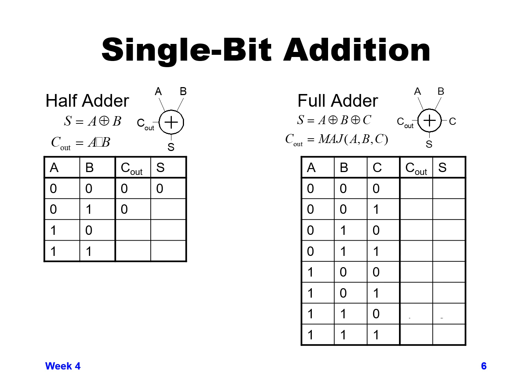When you have a 0 and a 1 coming in, you will have a 0 carry, but your sum will be 1 because 0 plus 1 is 1. The same is true of 1 and 0 coming in for A and B. Your sum is 1, but you have no carry coming out. And only if both A and B are 1 do you get a carry coming out. With A and B both being 1, that particular bit will sum to 0 with a carry.